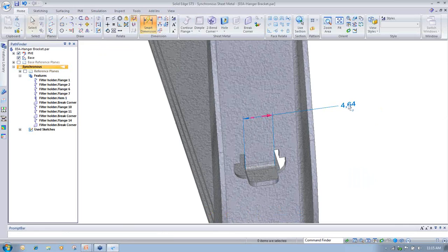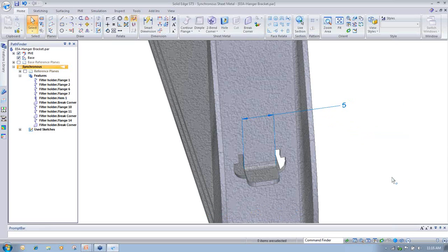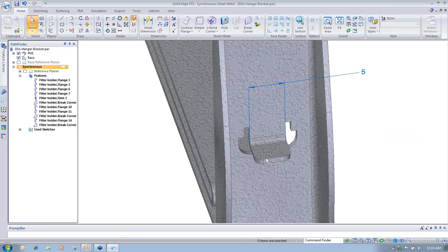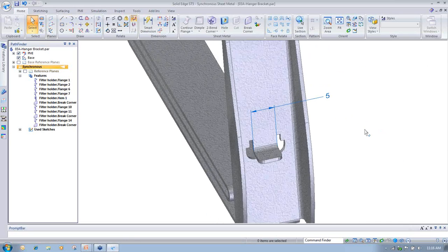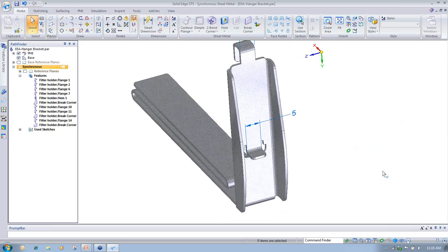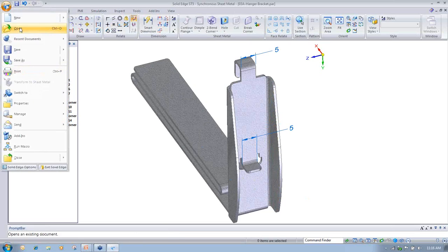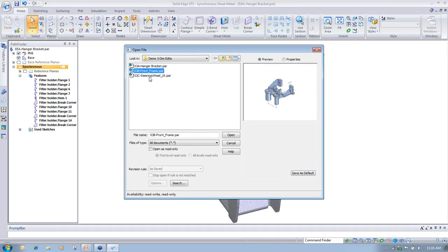Another thing that we can show you here really quick is on existing geometry that has cutouts associated in other geometry. We can also come in, give it a 5mm symmetric edit, and you can see that now it has updated and has included the cutouts. So that is a pretty substantial tool that will again keep all of your geometry associated and everything else working well together.